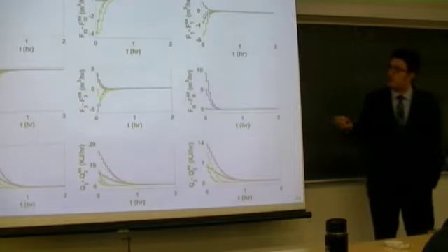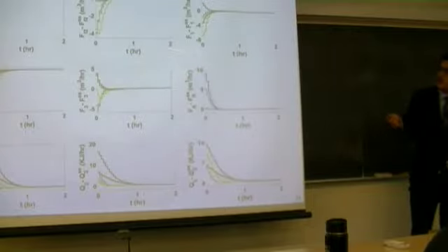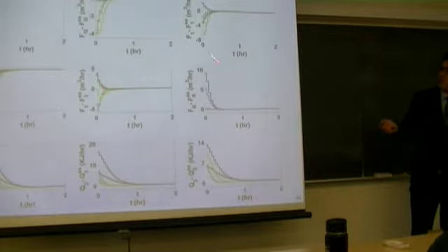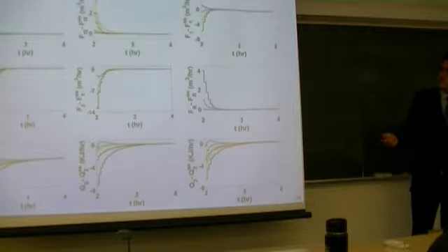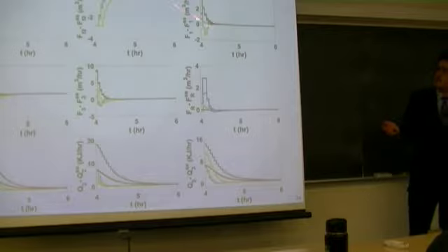This figure also shows the temporal profile of the control variables in discrete form, since it's a model predictive control problem, for the first tracking zone from 0 to 2 for all of the 9 manipulated inputs, the second tracking zone, and the third tracking zone. As you can see, I represent those manipulated inputs as a deviation from the steady state. As time evolves, the manipulated inputs converge to the steady state values.